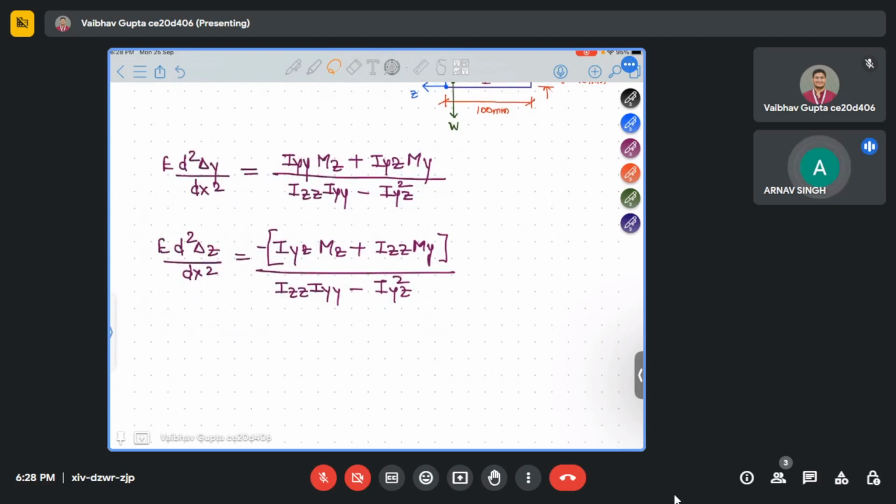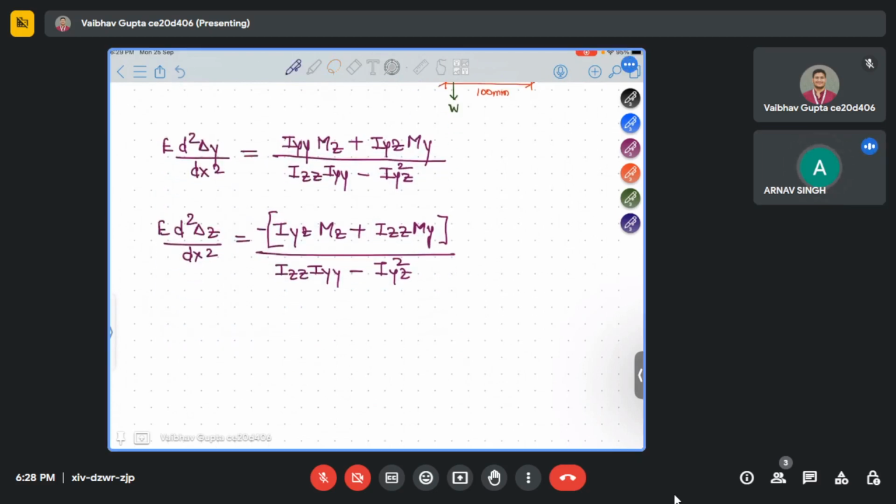Okay. Sir, displacement, no? Yeah, deflection is similar to displacement. In higher terms it will differ, but right now for you it is the same. Deflection means that if a simply supported beam is there, it will deflect like this. So what is the maximum deflection? This is del y. Okay. So in your case, it will deflect in z direction also. I cannot draw a 3D figure here, but it will deflect in z direction also. Okay, understood? So how to find these two values?